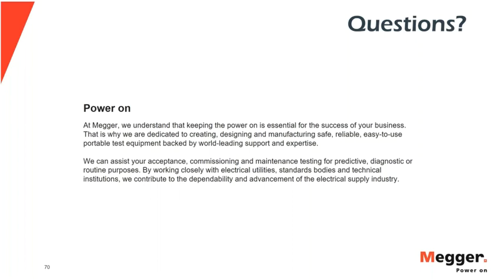Okay. When we're talking about life expectancy, it's like looking into some crystal balls. I mean, you cannot predict 100% what the future will be or what the life expectancy will be of a transformer. What you can make a technical statement on is the condition of your transformer at the time of the test. During operation, many things can happen, and you can say, yes, this transformer is in good condition to work for another 10 years. Fine. Under what conditions? Assuming that you're going to run some maintenance programs, assuming that you're going to keep a load control, assuming that you will keep everything under thermal conditions according to the specifications of your transformer.